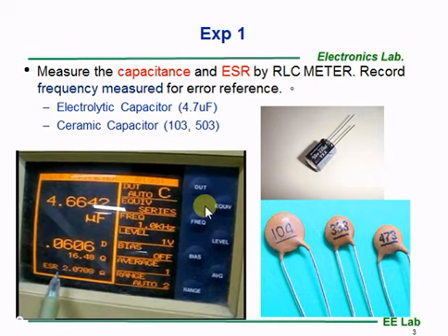In this figure, we've used 1 kHz to measure the 4.7 μF capacitor, with a result of 4.66 μF. This is an acceptable result. However, since we need to measure different capacitors, the 1 kHz may be considered too high. Therefore, we will use 100 Hz in this experiment.